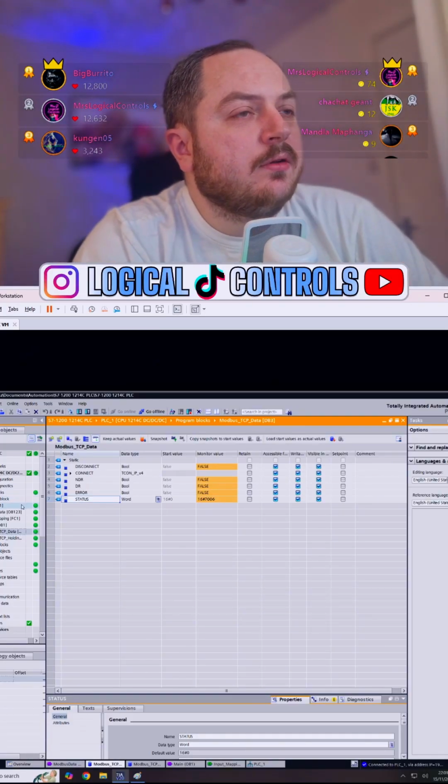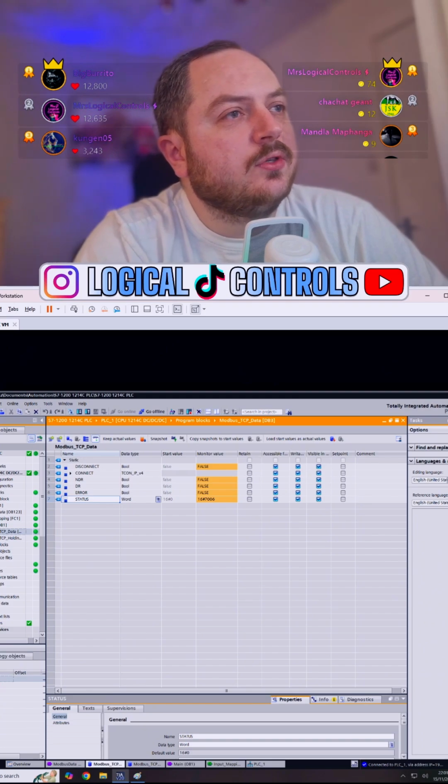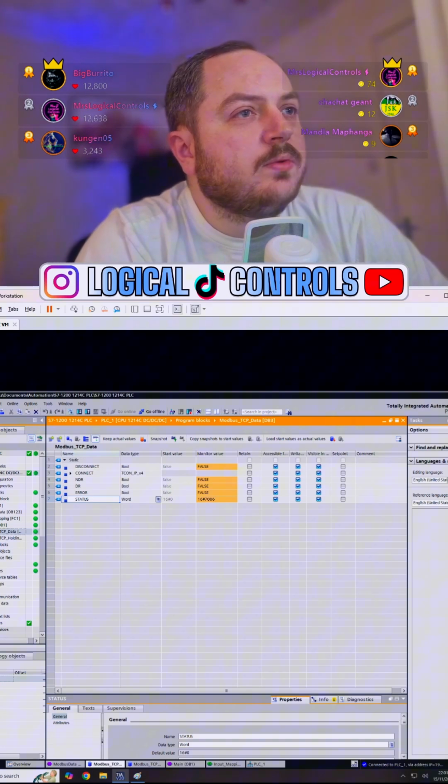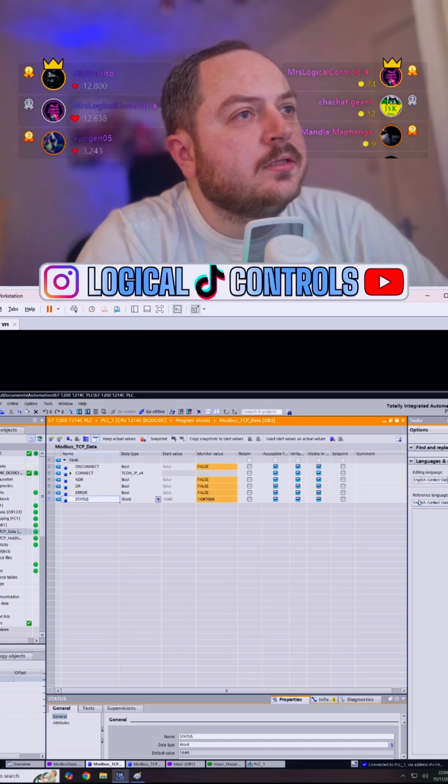Top tip, download the SCADA plugin for TIA. I'm new, but that one tripped me up big time. What? I don't know what the SCADA plugin is, Stephen. Yeah, I'm not sure, mate. I mean, store tags when you download, as I've tried to upload from a PLC and there were no tags.